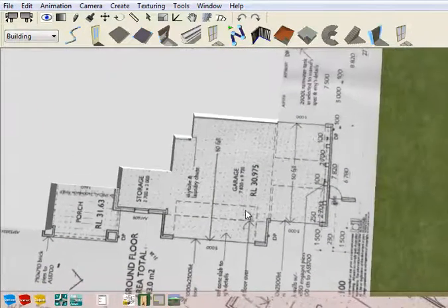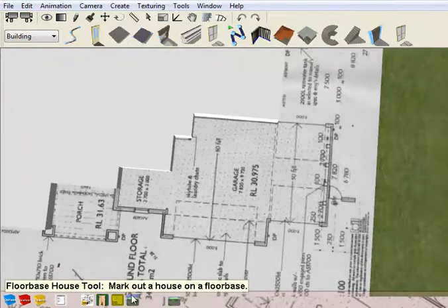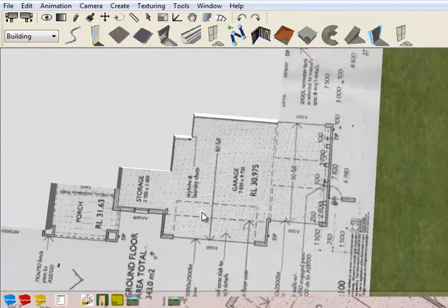To avoid doing that, simply select your floor-based foundation tool, press and hold the Shift key on your keyboard, and while you're holding that down, just click the left button on the surface where you want to create the object. And then let go of the Shift key, and you'll see you've got this little cross here. This indicates which object and orientation you're going to be drawing on.